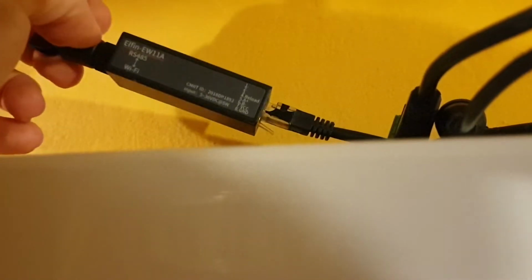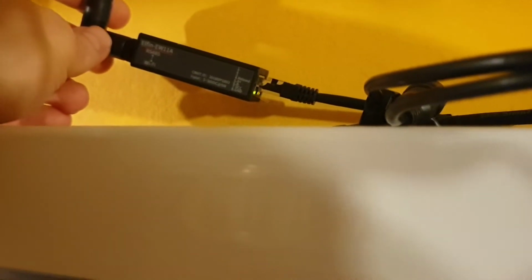But as the other choice, we can also use that second device, which is an adapter that converts RS485 to Wi-Fi. It encapsulates that RS485 Modbus protocol using the TCP/IP protocol, and it also acts as an access point, and it can connect to other devices. And as you can see, it has a pretty big antenna, so the connectivity is really great.